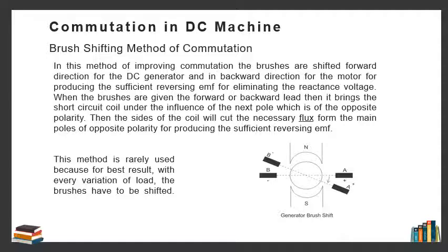So this is a diagram for generator brush shift. This method is rarely used because for best results, with every variation of load, the brushes have to be shifted. So this method is not used frequently.